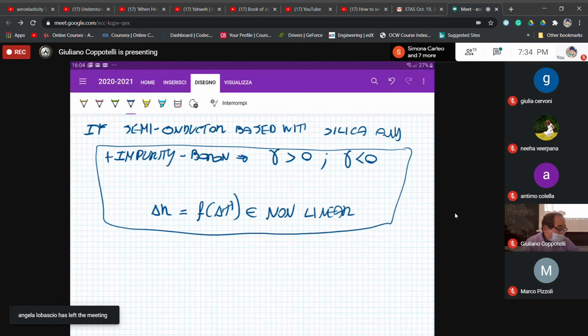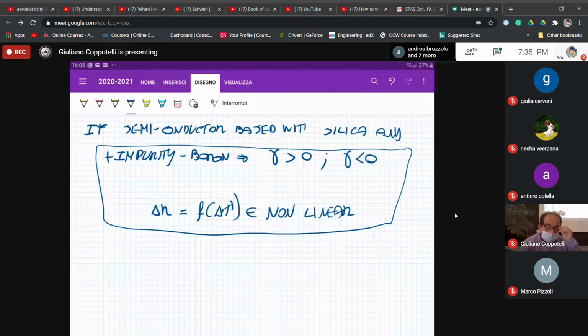So the question is about the difference in the linear thermal expansion in the bimetal thermometer. The higher is the difference, the lower will be the radius of curvature, and therefore the more sensitive is the thermometer.